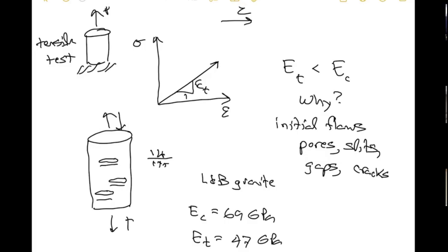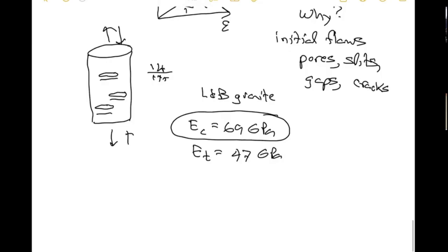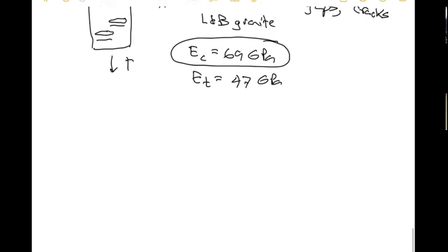However, in most cases, especially for design of rock mechanic structures, we usually just ignore this, and we almost always just take the modulus that you get during a UCS test. Okay, are you with me? Yep. Okay.